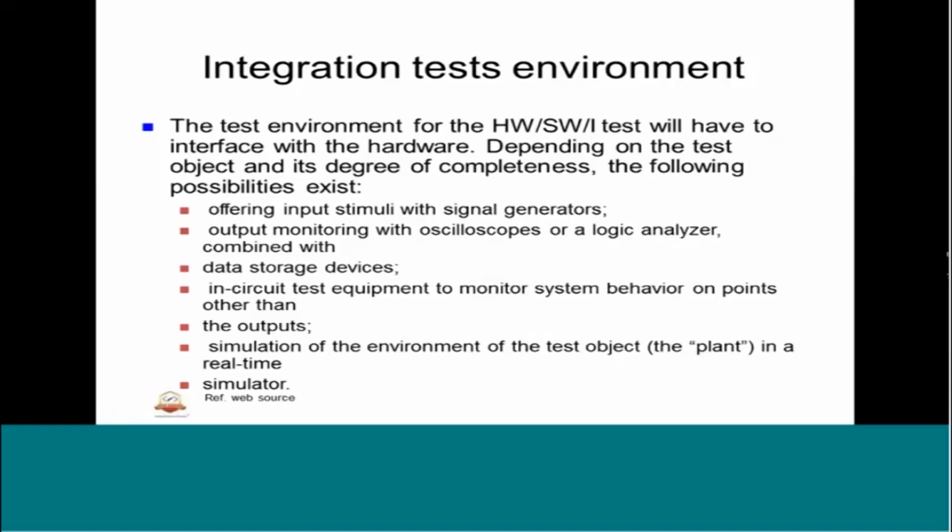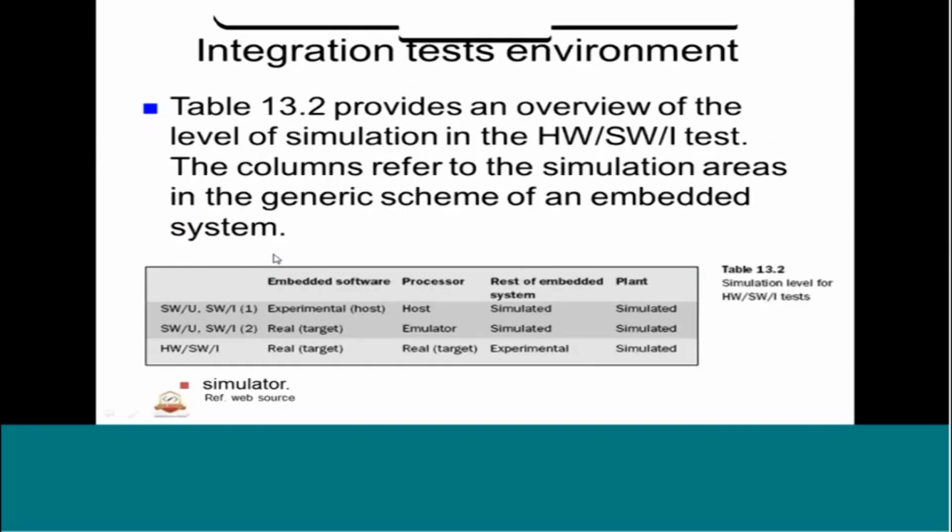So what we do is we have test hooks or interfaces from the target systems. With the help of those hooks, these tools will be plugged in, such as logic analyzers, oscilloscopes, or signal generators that can act as an input or output to conduct the test. That is the meaning of the test environment here.